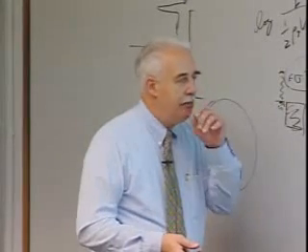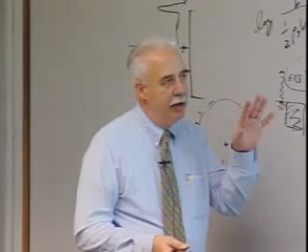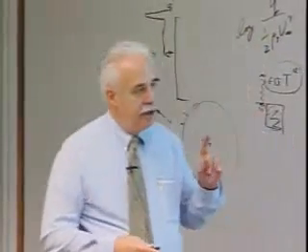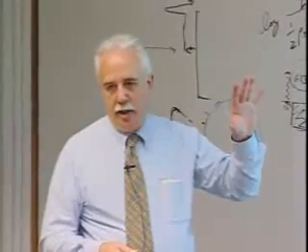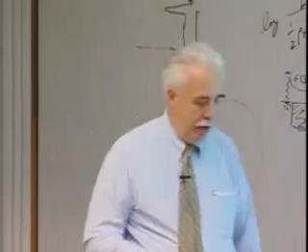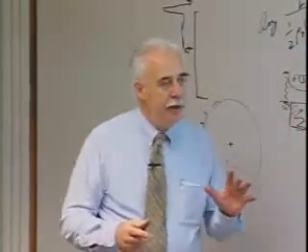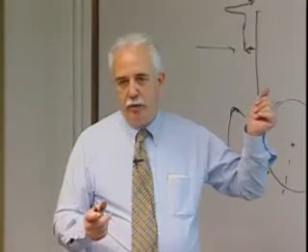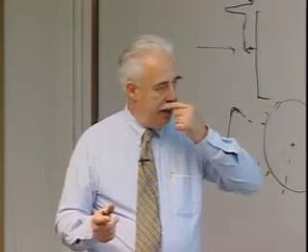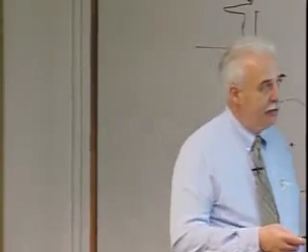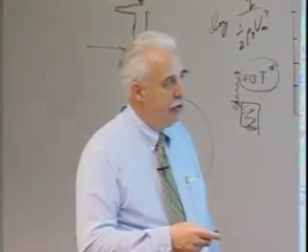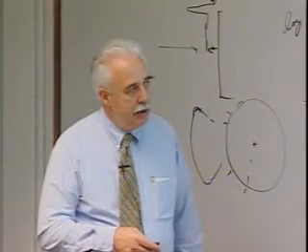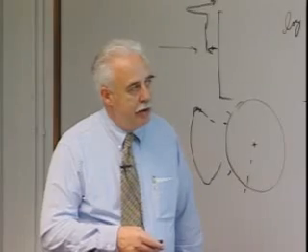Okay? Now, I mentioned 3 levels of aerothermodynamics. The design level, well, I'll get into the design level a little bit later. The first level was basically the Apollo technology. That was, we went to the wind tunnel, we correlated the distribution of heating on the shuttle relative to a reference, and we used a 1-foot sphere as a reference. And I gave that to the flight mechanics people and said, do not violate these constraints. So they developed the flight mechanics control and everything else to fly right along here.